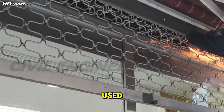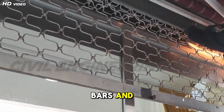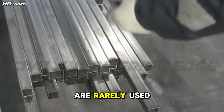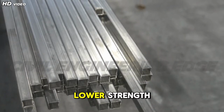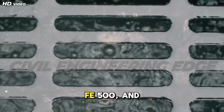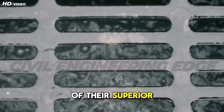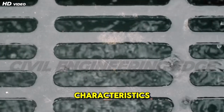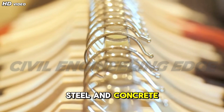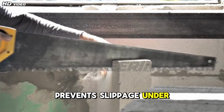The most commonly used reinforcement bars in reinforced concrete columns are mild steel bars and high-strength deformed bars. Mild steel bars, though ductile, are rarely used in modern construction due to their lower strength. High-strength deformed bars, such as Fe 415, Fe 500, and Fe 550, are widely used because of their superior tensile strength and bond characteristics. Deformed bars have ribs on their surface, which improve the bond between steel and concrete. This bond ensures effective stress transfer and prevents slippage under load.